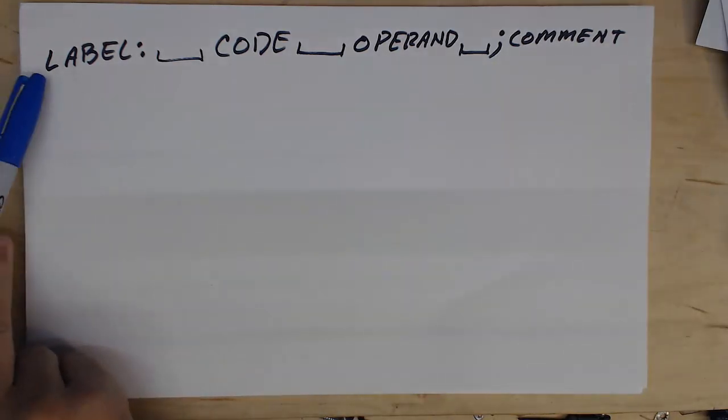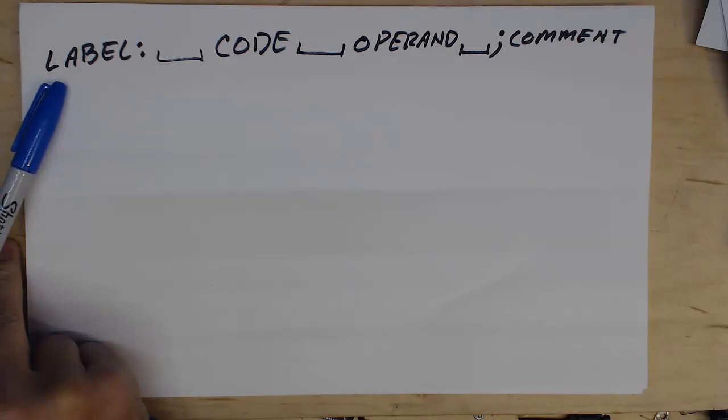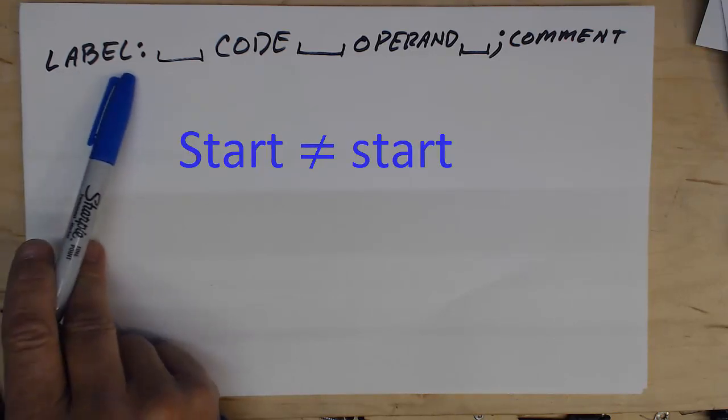Okay, so for the label, either uppercase or lowercase is probably okay. It depends on the assembler. The assembler may even ignore the case, but if the assembler does differentiate between upper and lower case, you have to be consistent in your labels. For example, if you have a label called START and you capitalize it, and you later refer to that as start with a lowercase s at the beginning, it's going to throw up an undefined label error. So you need to be consistent in how you do your labels.